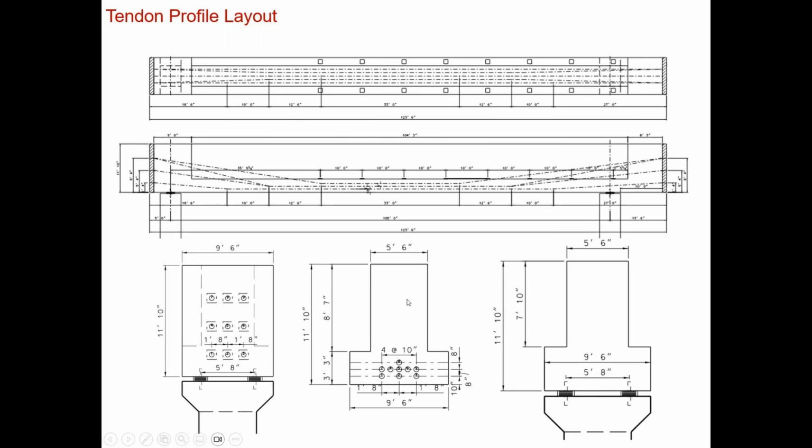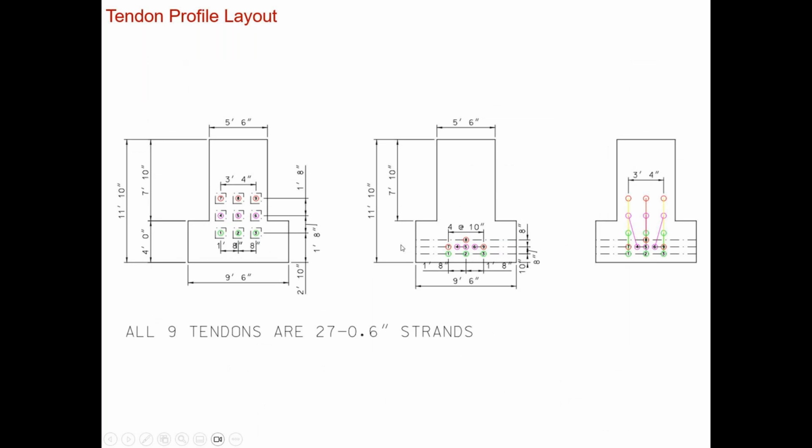And of course, for this bend, we decided to use this scheme of having the bearings with the anchors, even though all the loading combinations ended up with unequal compression forces on the two bearings. We still wanted to have anchors for any unforeseen loading effect that can result in any tension force on one side. Of course, the bearings never carry tension forces, so you want to make sure that you have anchors that, in this situation, are still capable of transferring the load to the columns and safely to the foundations.